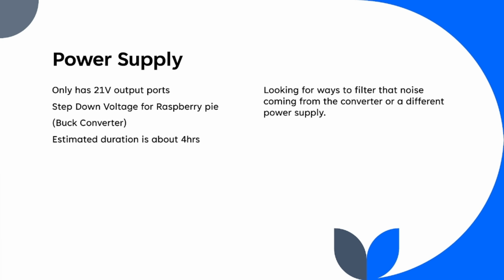That noise is caused by the switching action, which creates ripples in the voltage and current. Ways to fix that are to implement filters, like an LC circuit filter at the input and output. Another way is to enclose the converter in a metal box, which helps with the radiated noise.